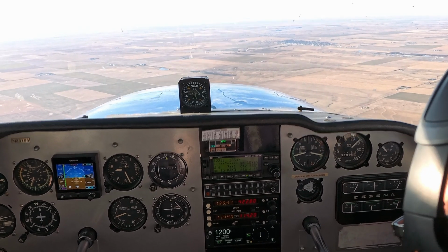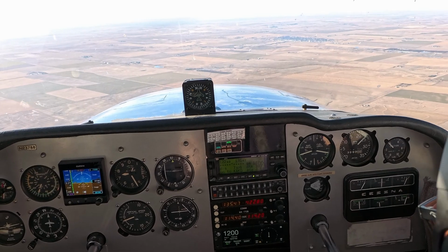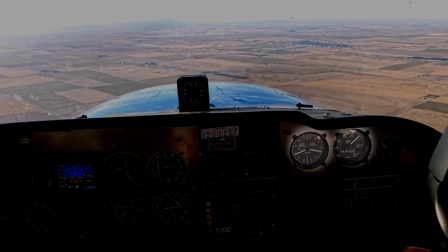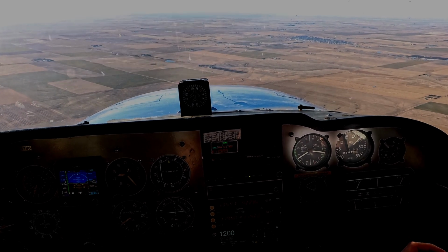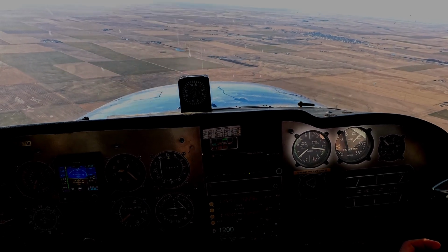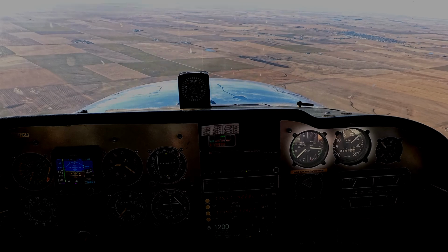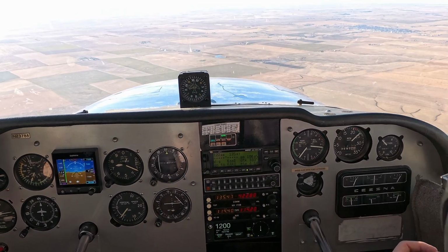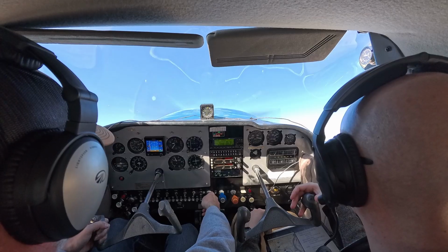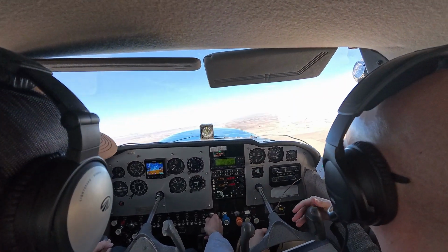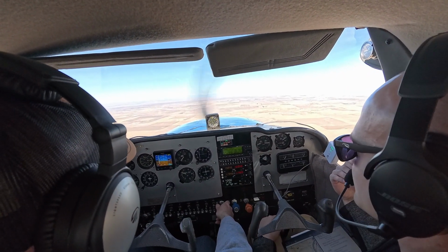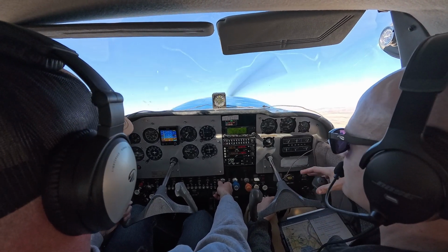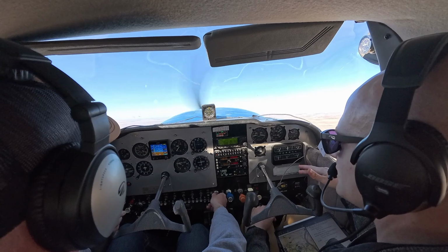It's important to note that variations in airspeed and variations in throttle will result in changes with your propeller governor. However, these changes will happen so quickly you should not necessarily see a change in RPM on your tachometer. The only exception would be if you've made aggressive power changes or aggressive pitch control movements where a momentary rise or momentary decrease in RPM might be expected. If this occurs, this is normal. This is your governor just taking a second to catch up.